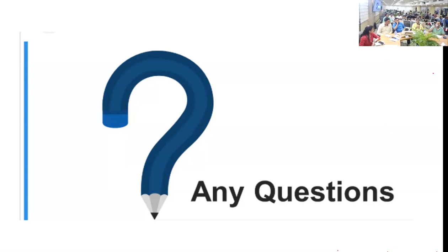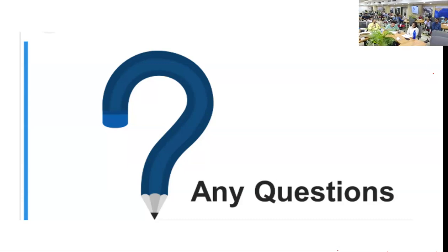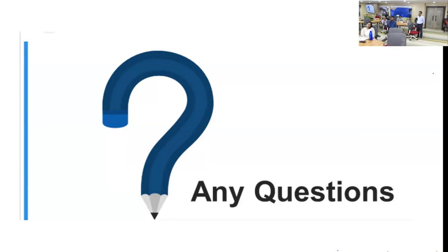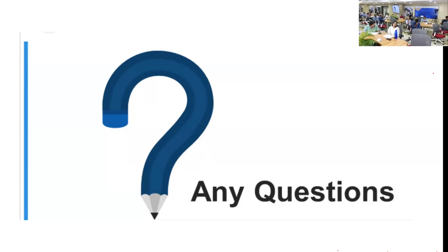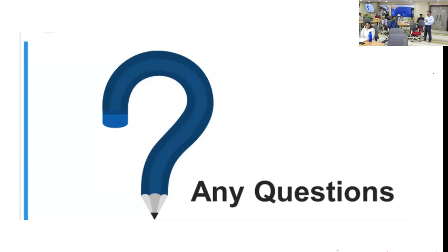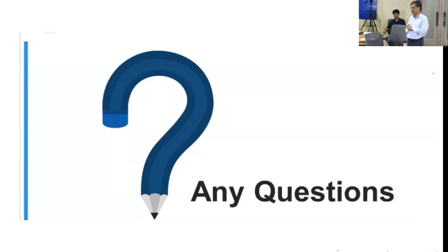One more question, sir. You mentioned the lab permeability also. I want to know how valid or how useful the lab permeability results are when we do the field permeability, or how reliably they can be interpreted in the actual field permeability case, sir? I said that is a problem. That is a gap. In the lab, we are talking about how much water goes through by gravity. And also at what density I am compacting and measuring the permeability, and at what moisture content.